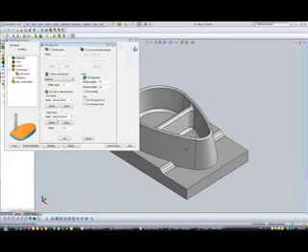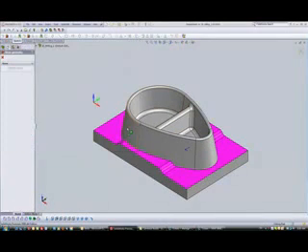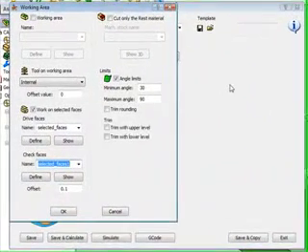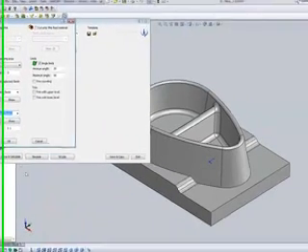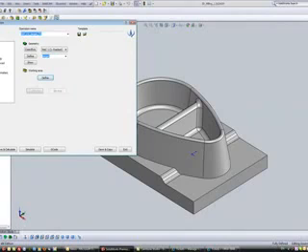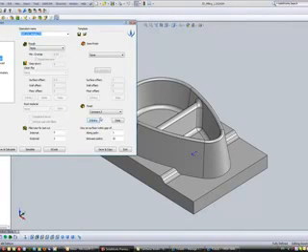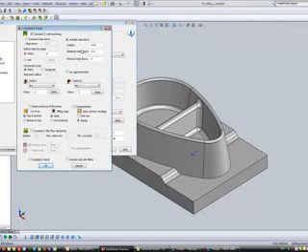Now in our check faces, we actually have the floors themselves from the outside, and we're just going to make sure that we stay away from those floors by 0.1 millimeters as an offset to make sure we do not touch those floors itself.